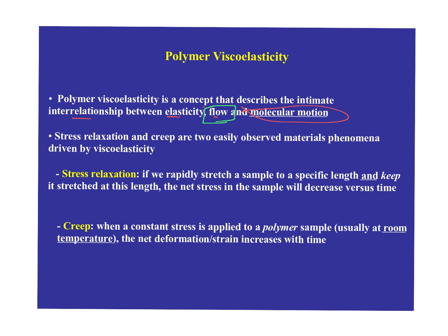But first, a couple of other things that are related to that. We have stress relaxation and creep, two easily observed materials phenomena. We're all familiar with creep. We've learned about creep usually for high temperatures for metals or ceramics, especially very high temperature creep for ceramics. Metals are not so high temperature, but in those contexts, we worry about creep at around 1,000 degrees or so. With polymers, it can happen at room temperature.